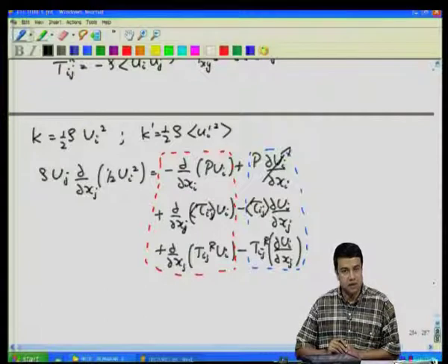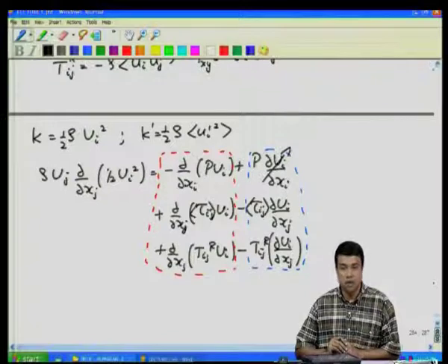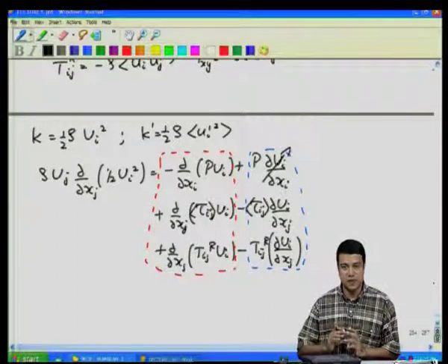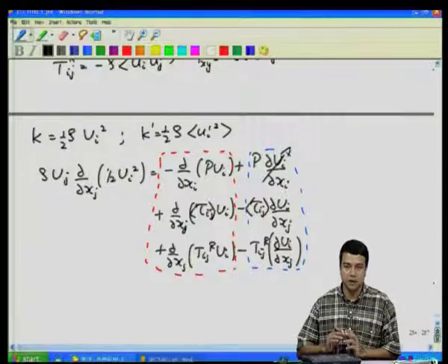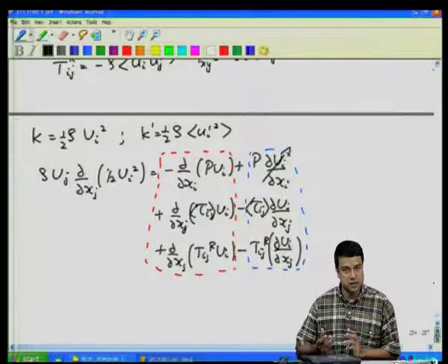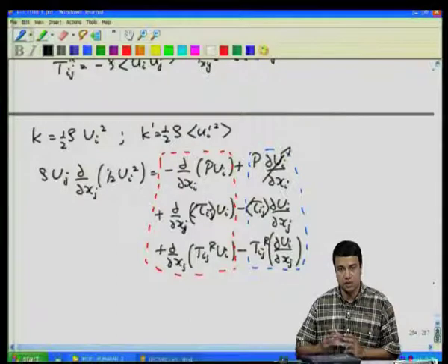The last term is the dissipation due to the Reynolds stress. So, this is not a viscous dissipation, it is a dissipation due to the fluctuating energy of the molecules. The viscous dissipation of course converts mechanical energy into heat energy, into thermal energy, and increases the temperature. The Reynolds stress does not convert it into thermal energy, because it does not increase the fluctuating velocity of the molecules. It increases the fluid fluctuating velocity. So, it does not convert it into heat.